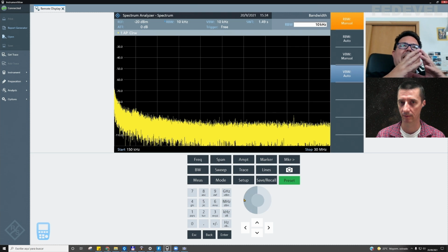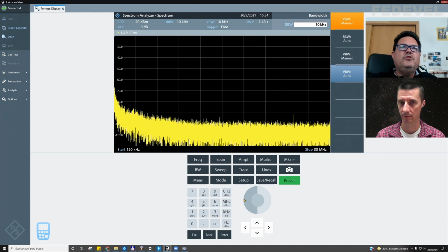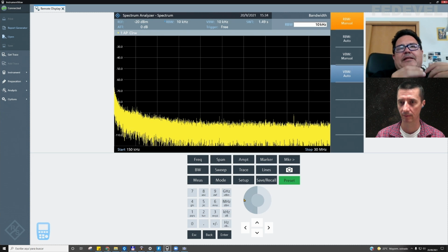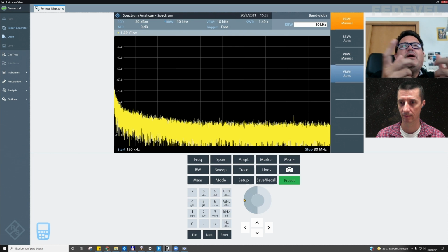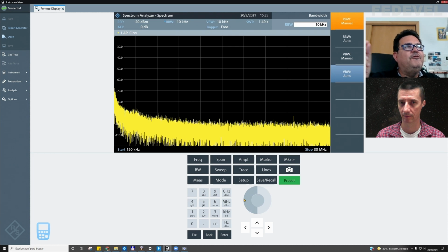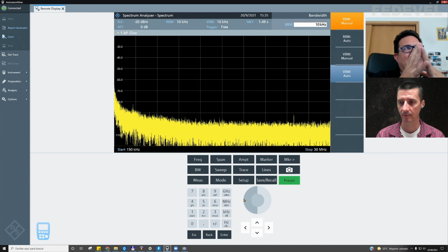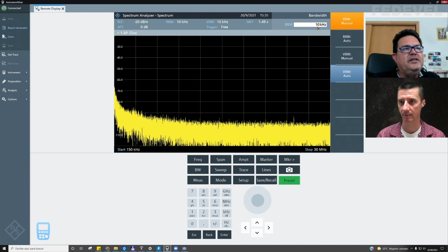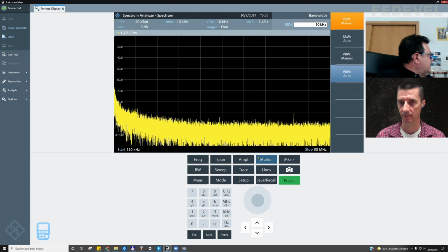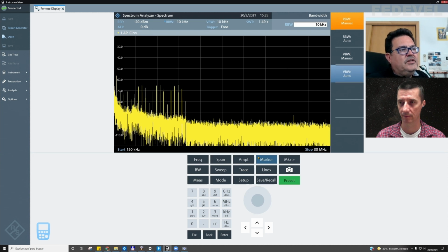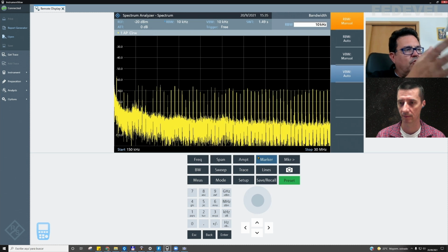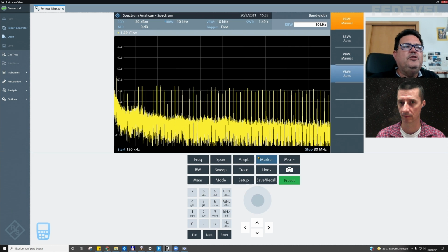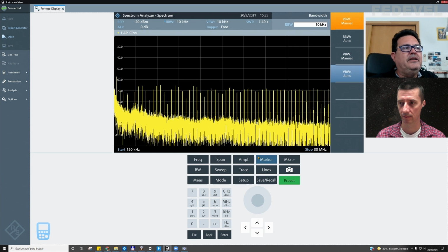So when you want to analyze a very big frequency range with a very small resolution bandwidth, it's not the same, but it's like in SPICE, sorry, when you are trying to simulate a very long time with a very small step. Calculation time. Yeah, I understand. Something like this. So the important thing is to have a good setup that you understand, because the idea is to replicate or be close to the situation in the laboratory for doing debugging or something like that.